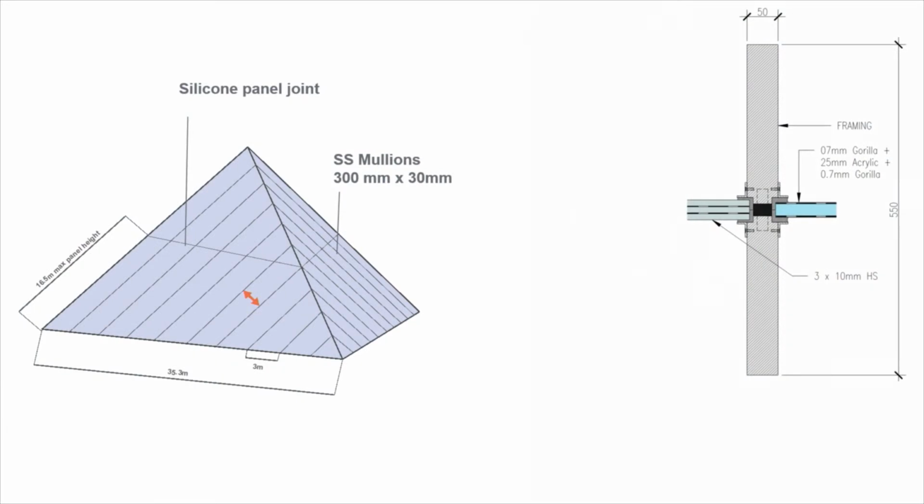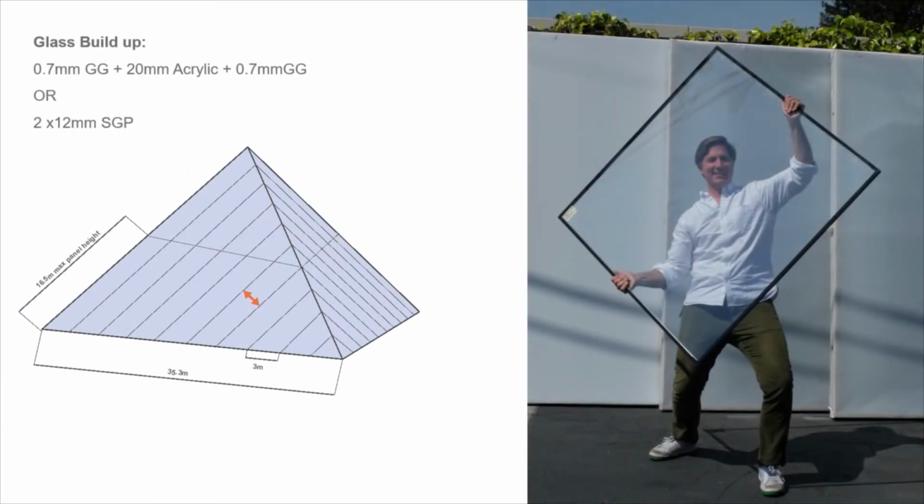So we quickly deviated from that and said, let's look at what we could achieve with a lightweight glass structure with intermediate steel framing. Could we get that to be a much lighter and more transparent structure on its own? What we quickly realized is that no matter how lightweight we make the glazing or the infill panels between the structure, the structure itself is so big that the steel framing ended up being so large just holding itself up, regardless of what kind of lightweight glass we put in, even thin glass. You end up with something that works, but again, is not a huge departure from the existing.